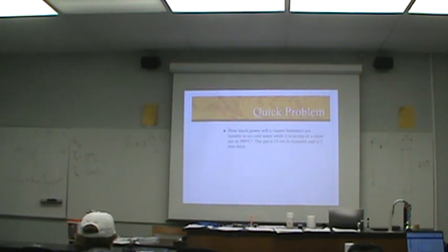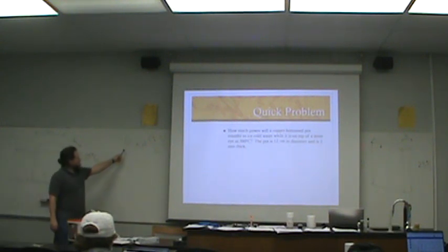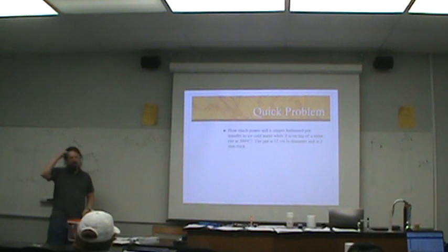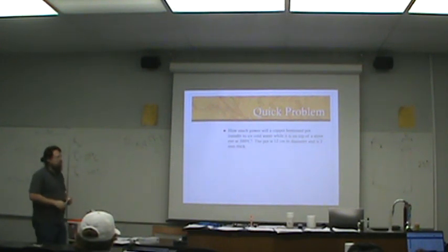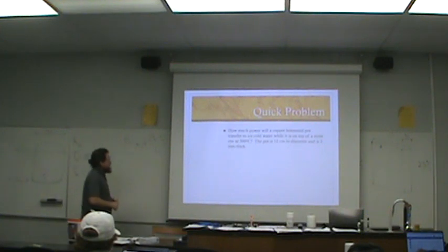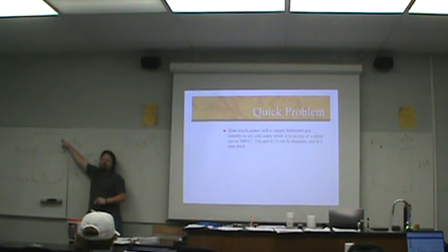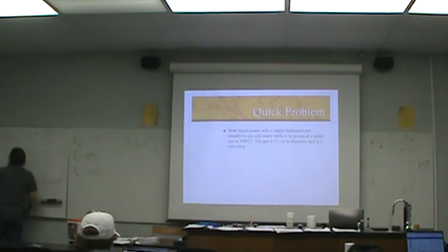So, with all the information that we're given, what do we need to do to be able to calculate the thermal power, the rate where thermal energy passes through this pot? All right, we need the surface area. The bottom is a circle. We know its diameter, so we just need to look up how to find the area of a circle, which is pi r squared.